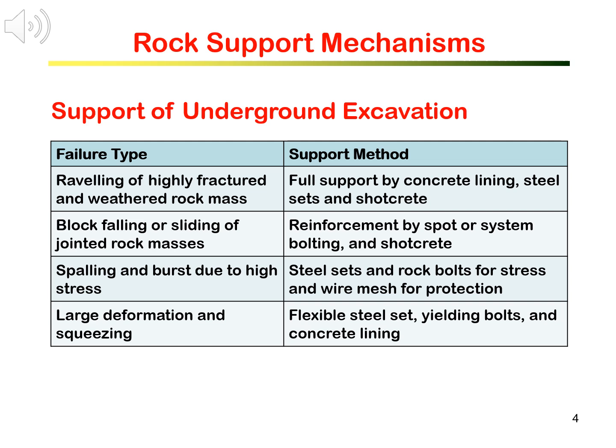For unstable ground of highly fractured and highly weathered rock mass, the excavated opening will not be able to stand without support. Therefore, we need to install full support quickly to prevent failure of the roof and sides, and even the face. In this case, the support is typically in the form of a structural ring of concrete or steel.